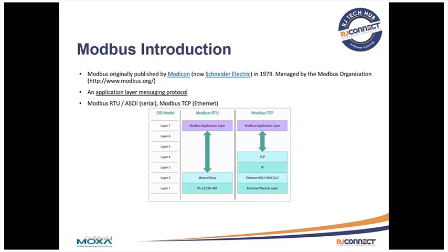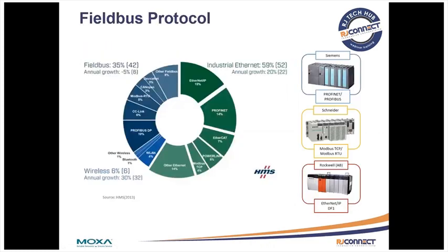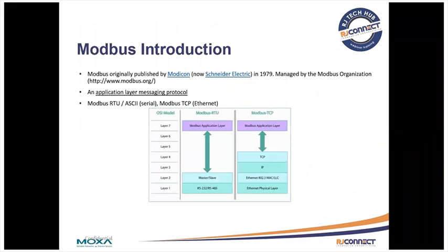All right guys, so let me just go back quickly, one slide. So these are field bus protocols, and the major players previously used serial-based protocols, but are now able to use Ethernet-based protocols such as Profinet and Ethernet IP, just to give a few examples. So on the next slide, I just want to introduce Modbus, originally published by the Modicon Group, which is now Schneider Electric, but is now managed by the Modbus organization.